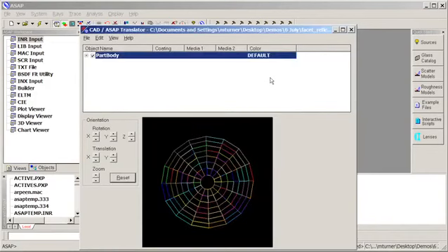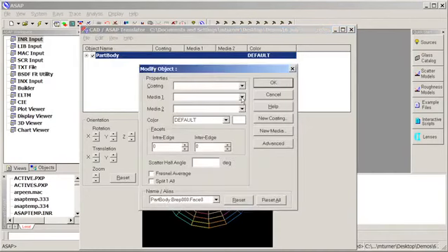And here's the part that's been imported into ASAP. And I can come into this importing option here, and I can define some new parameters. Since I know this is a reflecting surface, I can assign a reflecting coating to the object as a whole. I could also do this within my ASAP script as well, but I might as well do it in this location. I also can set up my interface properties, and in particular, I know my reflector is going to have